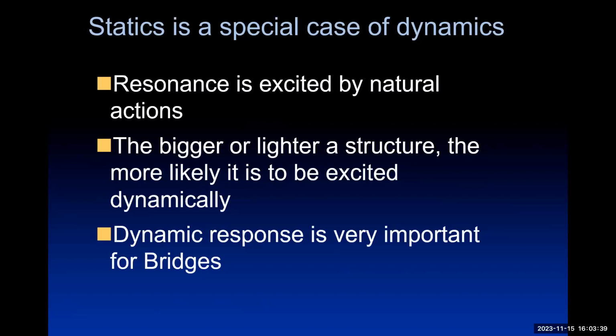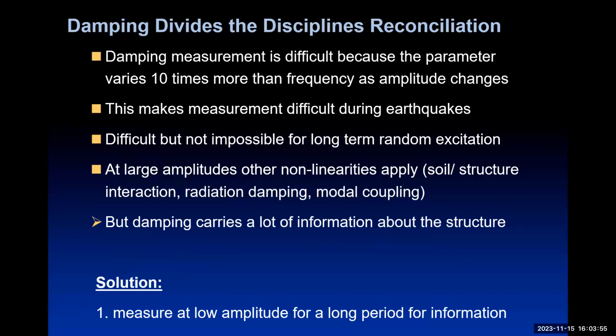The dynamic response is very important for bridges. Why? Because the frequencies are lower and the wind blows every day at the low speeds, which are important for creating aerodynamic instabilities. So damping actually divides wind and earthquake engineers. Why?